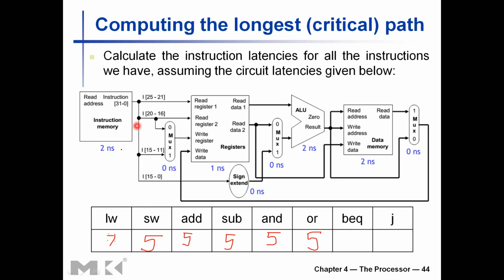Branch instruction, you read from the instruction memory, then you have to read 2 operands from the register file. The ALU needs to subtract those operands and decide the zero output value, whether the result is 0 or not. Then go and update the program counter value, right? The adder will happen in parallel to the ALU. If you remember, so how long will that take?